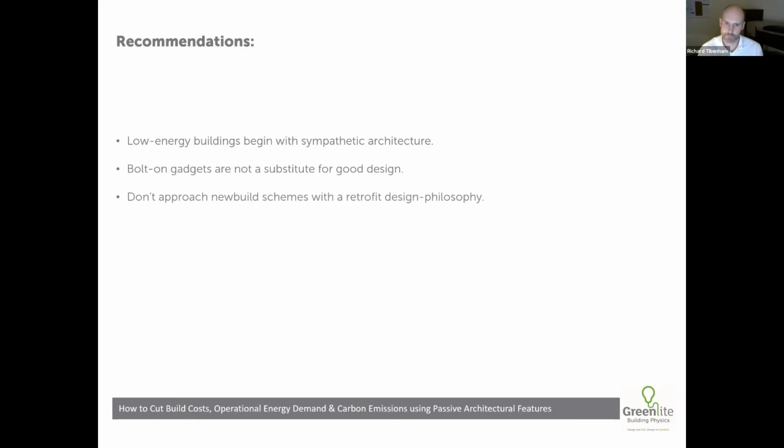Don't approach new build schemes with a retrofit design philosophy. It's the same type of thing really. Don't just build a building the way that you otherwise would do and then tack on heat pumps and PV cells as if you were dealing with a retrofit project. In terms of retrofit, your options are limited. You can't rotate the building around 90 degrees. You can't change the roof design, for example, that easily. Whereas at the new build stage, you've really got a fairly blank sheet and you can optimize the aspects that we've been through today.